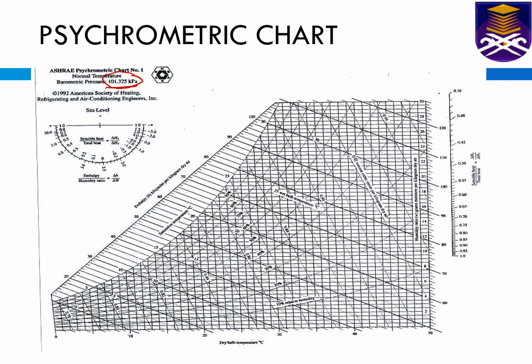So here you have the dry bulb temperature, read from the thermometer. And then you have another one here, which is called the wet bulb temperature. Let's say that you got the reading of dry bulb temperature equal to 30 degrees Celsius and the wet bulb temperature equal to 25 degrees Celsius. If you plot this and come here, then you can read the point at these conditions. So what other parameters or variables do you have here?